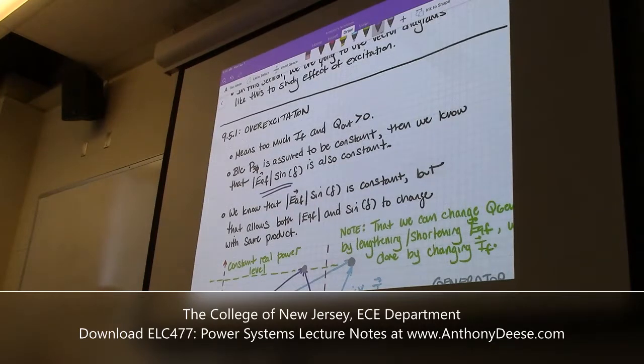there are so many different components in a power system with varying time constants that you can have different types of transients. You can have transients that are transient from the point of view of the motor only. You can have transients that are so fast that they actually affect a transient response within the transmission lines or other components in the system. So there are different categories of transient.